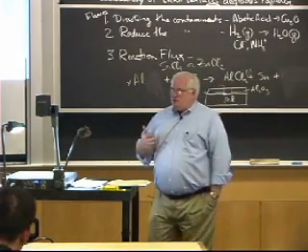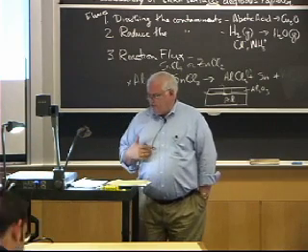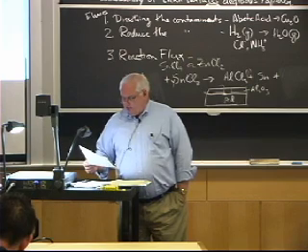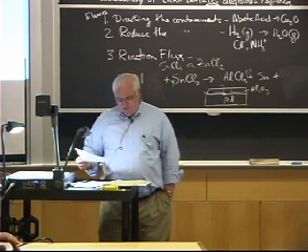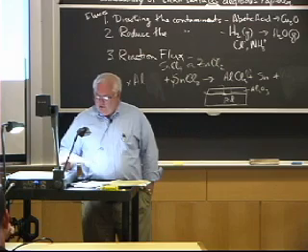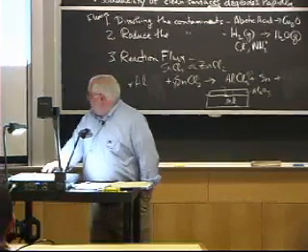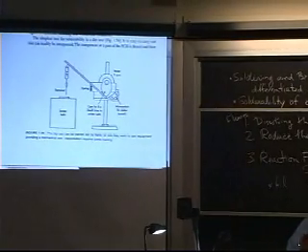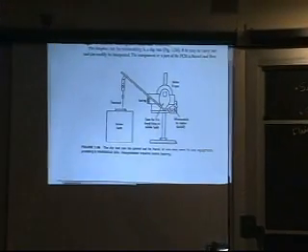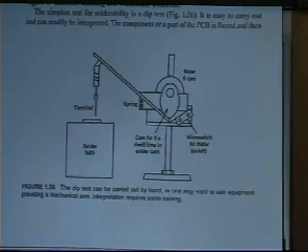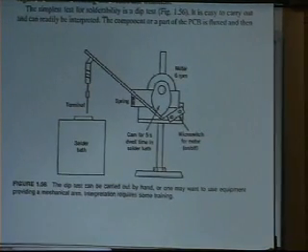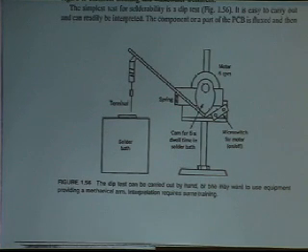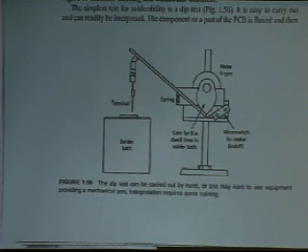Okay. So in the soldering business, you have to have ways to determine whether you've got good solder joints, or good solderability. It turns out there are various ways. One of these tests is called the dip test. I told you before, there's not a lot of quantitative stuff to soldering. There actually is some good science and research that's been done, so we understand a fair amount about soldering. But it's such a complex process, it's hard to really put good numbers on it. But for quality control, people are trying to get some quantification.